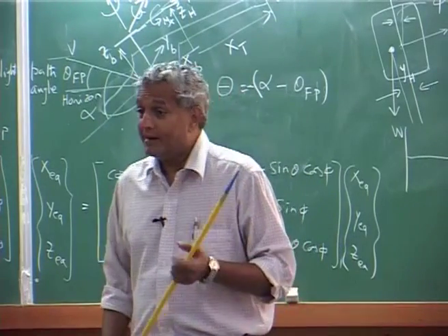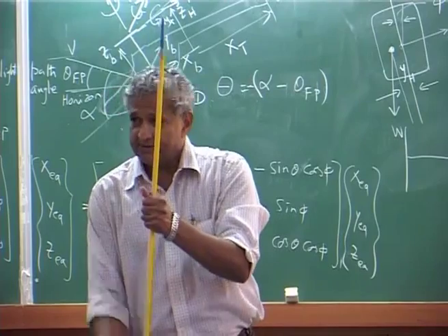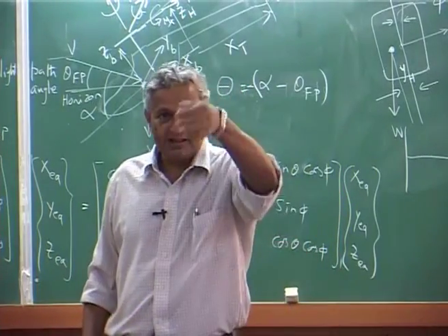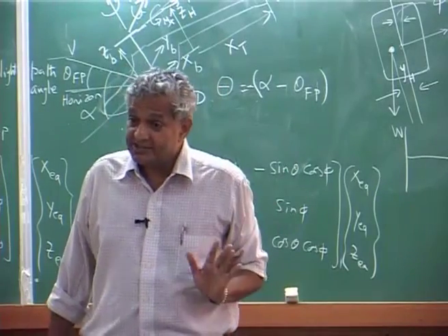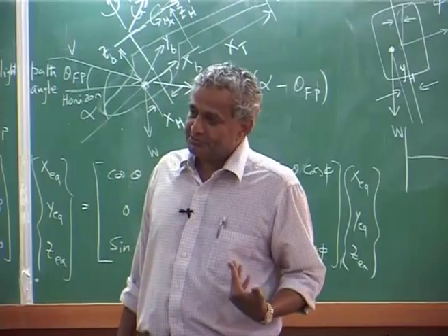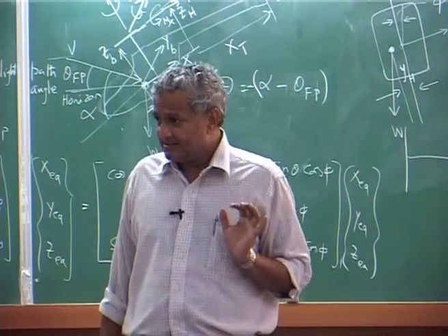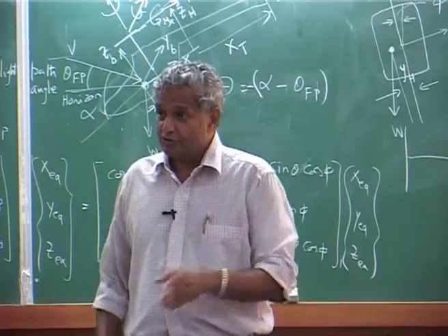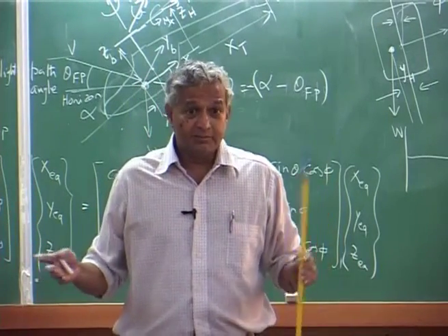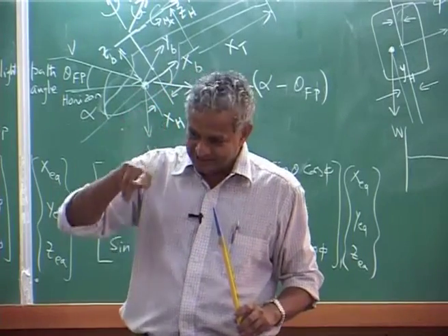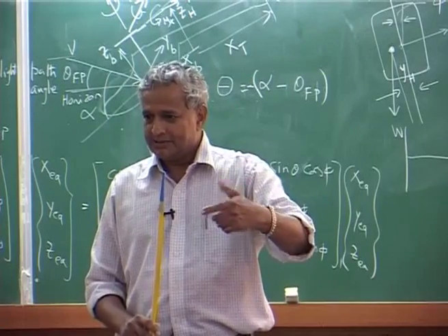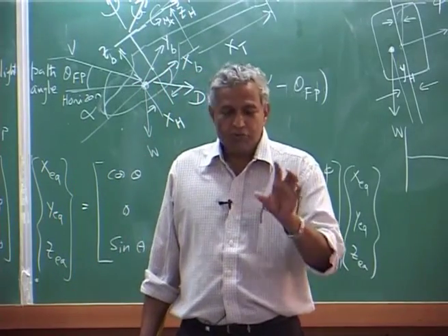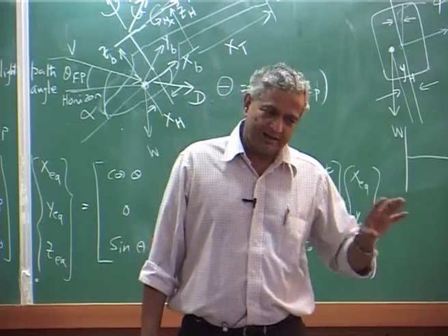There you do not go and balance the thrust, because it is held. Whatever force that comes, it is not that it is equal to weight. So, thrust equation is out. You may directly solve what the developed force is, there is no equilibrium equation. In a wind tunnel, what people do is they give prescribed collective, prescribed cyclic, prescribed theta naught, 1C, 1S. Now, find the response of the blade, but for that you need to know inflow. So, they will give the shaft angle, that is all, but you do not know thrust, you follow. So, you have to get the thrust and then get the inflow and then get all the response quantities. So, depending on the situation you use that particular set of equations and solve them.